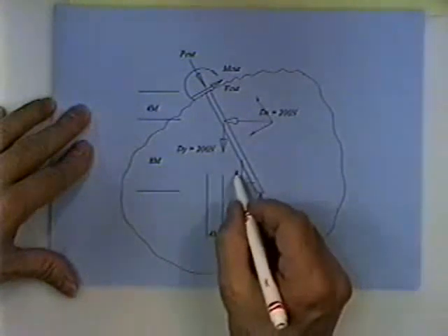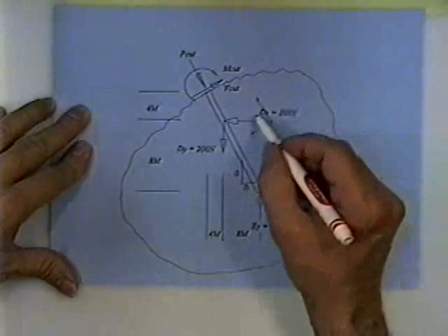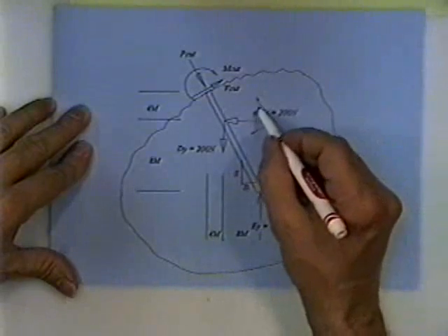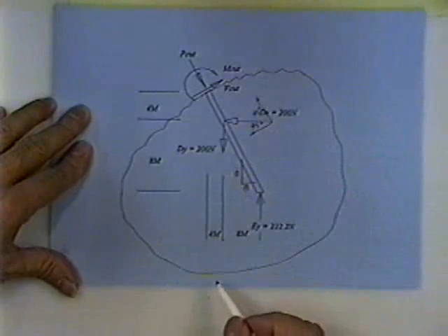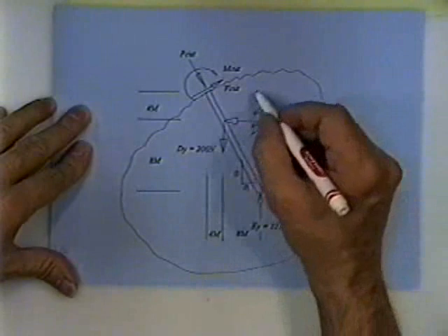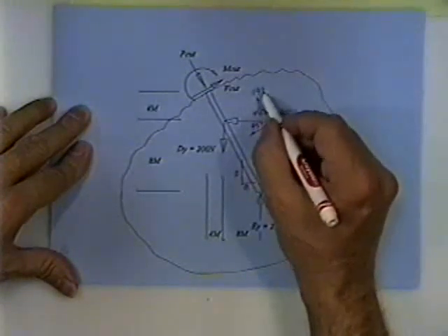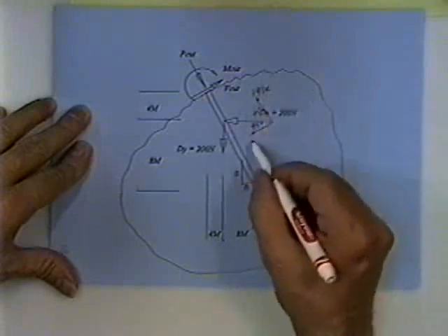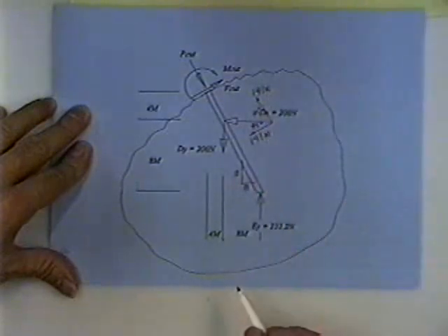It's not drawn much like it, is it? It's an 8 by 8 angle, and therefore you simply put 45 degrees in here and 45 degrees in here and multiply the 200 Newton force times cosine of 45 degrees. 141 newtons and 141 newtons.